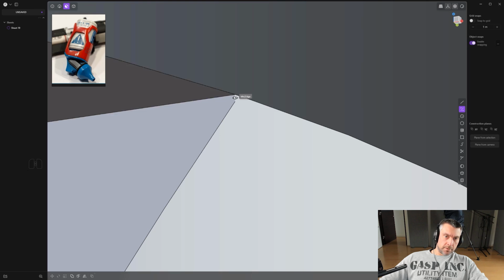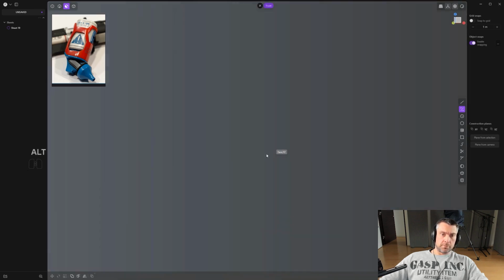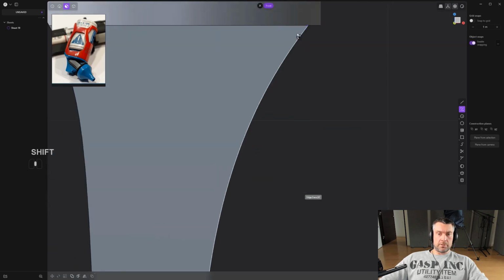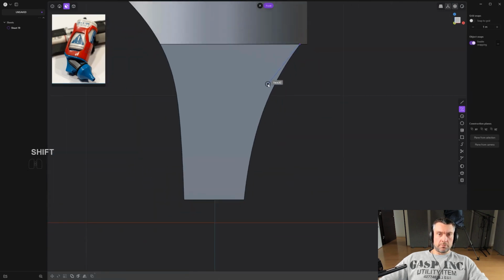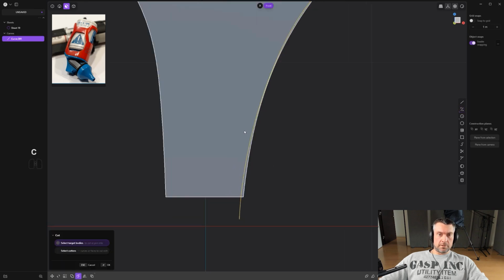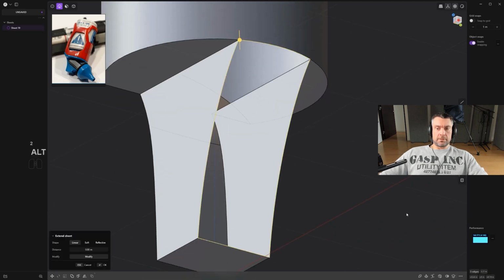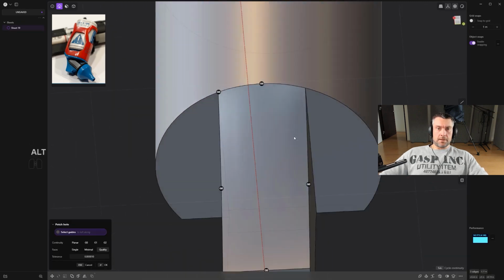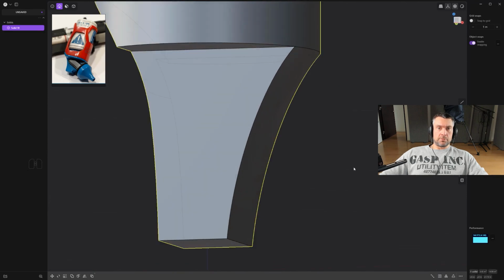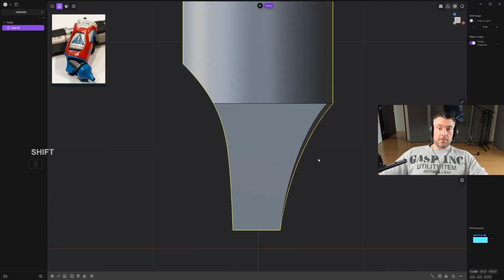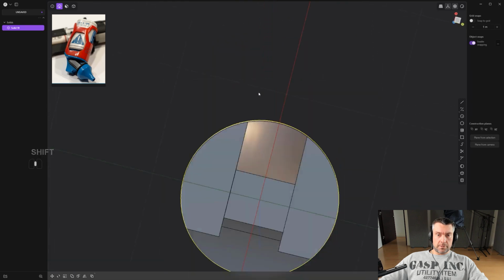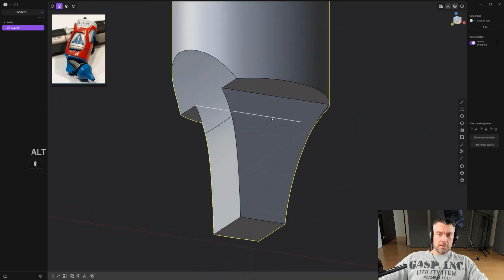So we want to fix this. Let's grab this point here one more time. Go to side view, zoom out, and let's just cut this one more time. Yeah. So very closely here, like this. Okay, and then C, cut, remove it, and now it should be perfect. So now I can Alt click this and patch it, and G0 on every single corner, and that looks good. Okay, so there we go, that looks cool, and now we can have some fun.